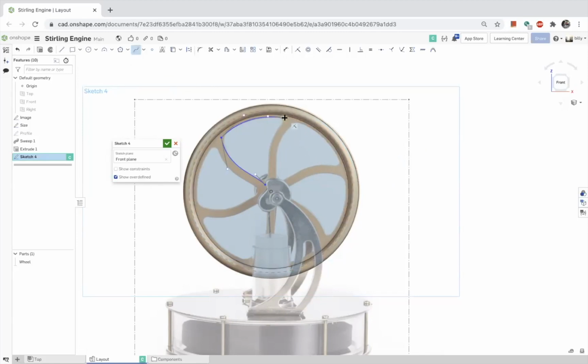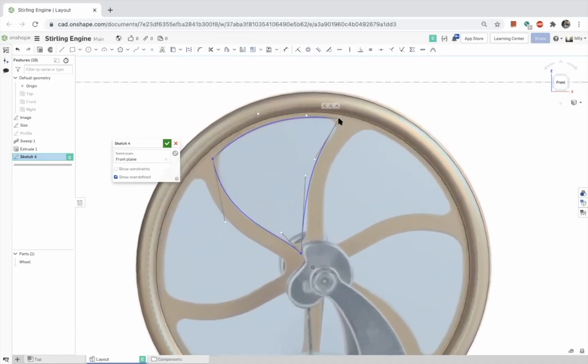So let me continue on. I'm going to go here to here, and I'm going to try to get these to match up to that shape. Now, notice how it's also picking up vertical. So if I hold the shift key down, it stops that. Yeah, that is annoying. A lot of times that I'm dragging splines around, I want to, so let me drag that over a little bit, move that up a little bit. And I'm holding the shift key down now, so I'm stopping all its nastiness. And let me drag that over. All right, and that's probably good enough for the purpose of this discussion right now. All right, you like that?